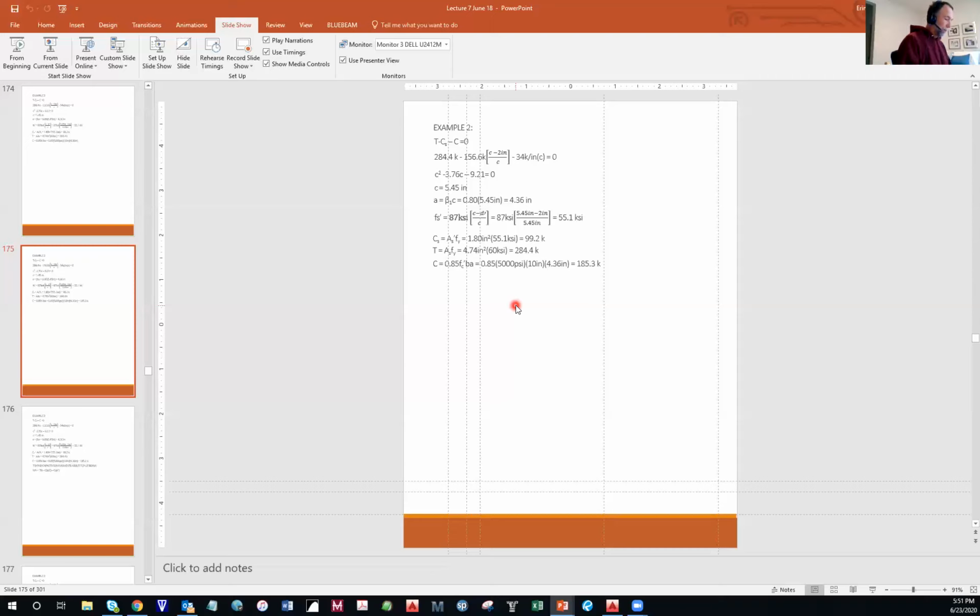Okay. So the design problems that they have, they give you a 5.9 and a 5.10. That's all they give you is 5.9 and 5.10. Okay, so 5.9, they give you a demand and they give you all the dimensions, but they don't tell you how much steel you have. So steel As and A prime s are unknown. So what they did is they took the total demand